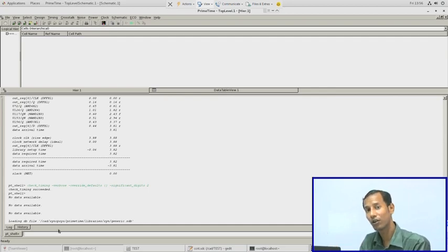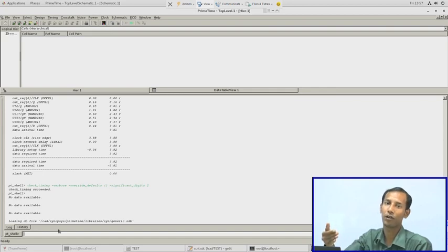But as we are not covering the simulation aspects here, unless we do the simulation, I am not applying the test vectors, so I am not able to generate the switching activity file, which I would put here to show you that the power consumption is happening because of the dynamic power. So I will provide that information as a supplement to this lecture.